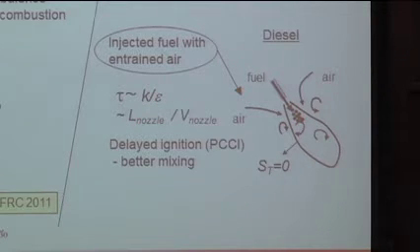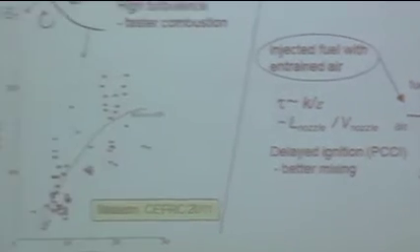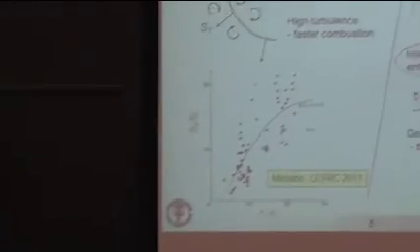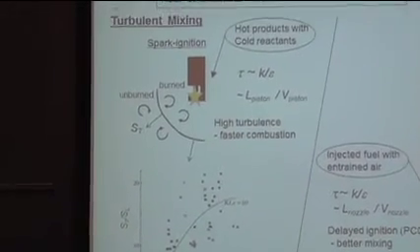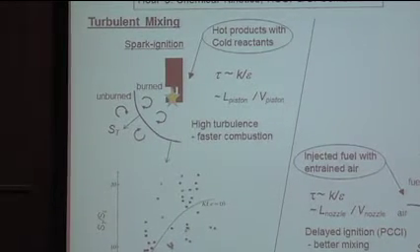Are we moving more towards direct injection now, and therefore dealing with these same kinds of mixing issues? Absolutely. Yeah, and in fact, we'll be talking more about that. So one more question. What role does gas expansion play in increasing that burning velocity? That's definitely an issue, because these now are high temperature gases that expand, so you see an effective faster flame propagation. Because the ratio of the turbulent to the laminar is just a couple of tenths. Right, and that's probably part of the reason for some of this scatter here. Yeah, thanks.